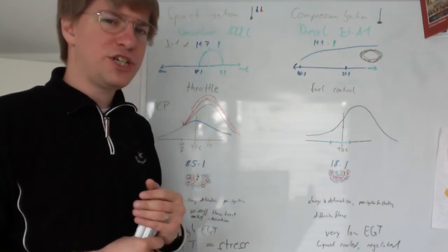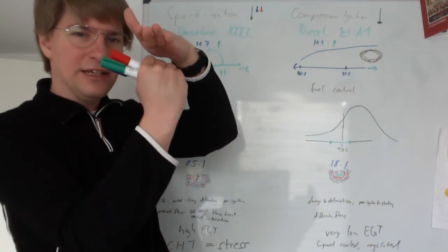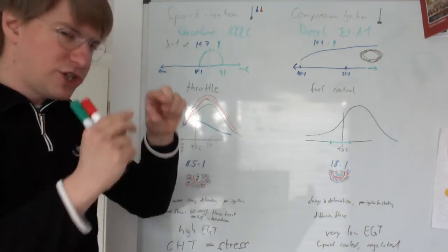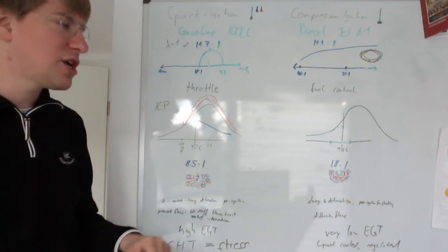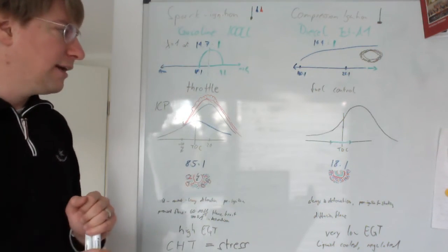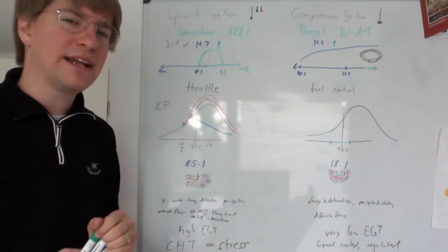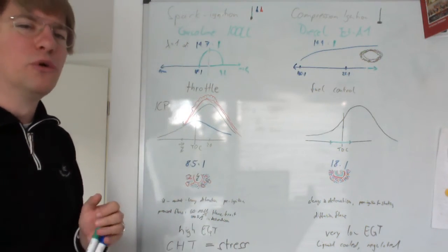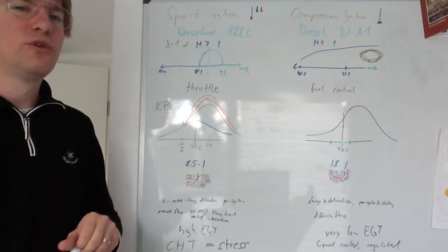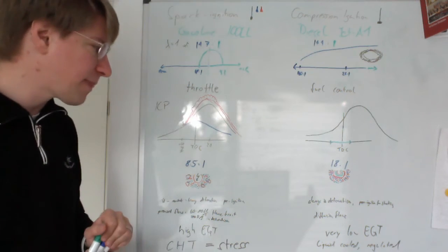In order to achieve this, of course, the engine needs to be stronger, the head needs to be stronger, the head needs to be a lot tighter to achieve this super tiny combustion chamber at top dead center. And the Mercedes 190D actually ran at a whopping 22:1 compression ratio in their diesel engines.